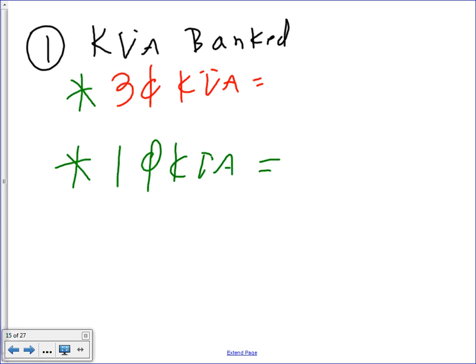The blank is always B. In an open delta center tap, B. In an open delta only, you don't have single phase loads. It's all three phase. It has to be open delta center tapped, then it's B also. Okay, now take this kVA bank.